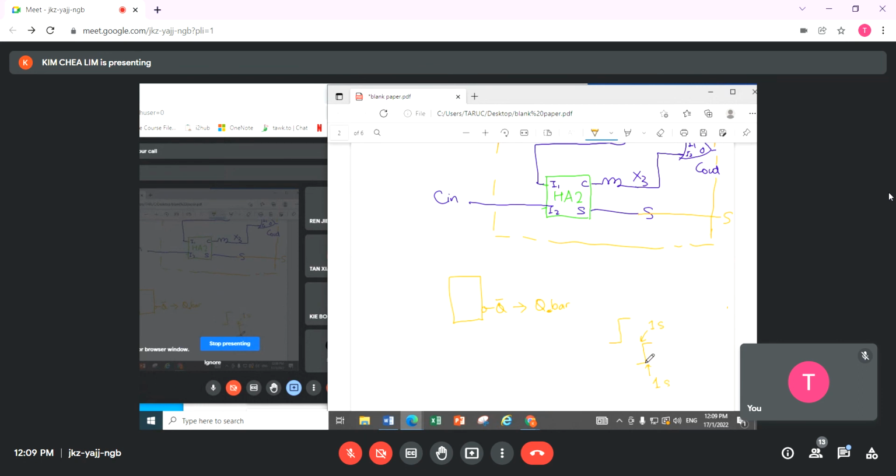So at 1 second you are at 0, same thing at 1 second also you are at 1. Logic 1. So this is logic 0, this is logic 1. Therefore this one here is called an event in VHDL. Very short duration and no time difference. Things happen, so this is the part we call an event.